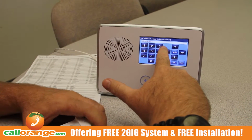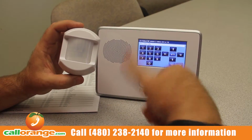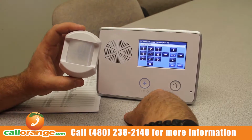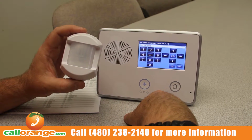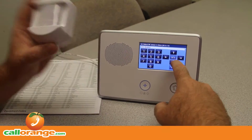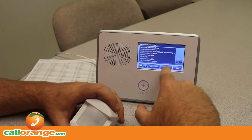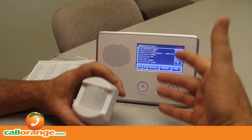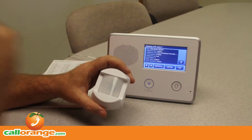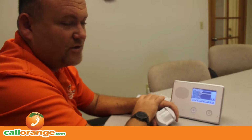It's asking for the chime. Always do not put, remember we did voice on the front door and the other windows? Never put the voice on these, because every time you're walking around the house, you're going to hear the panel say motion sensor. So always leave that disabled on the motions, okay? There you go. Now if I wanted to edit the next, I'd do my next sensor, and so on and so on. So all you do is go in there and pick what it is, and then label it what you want it to label it, and then you just go through the motions over and over again.